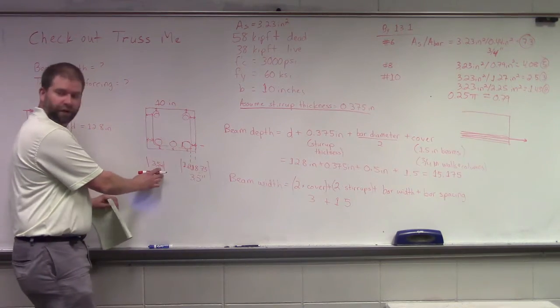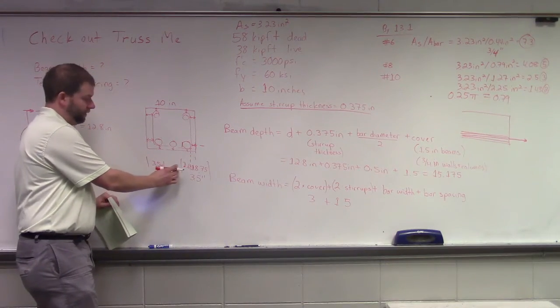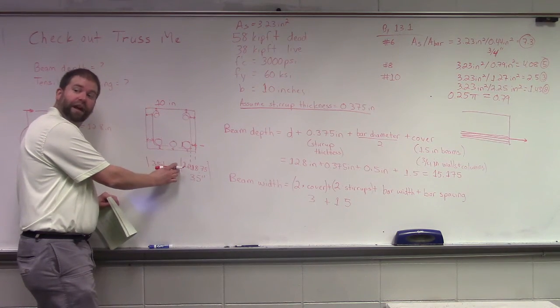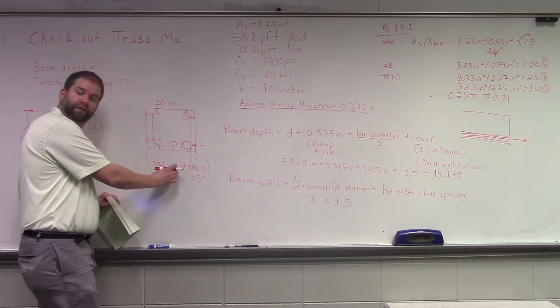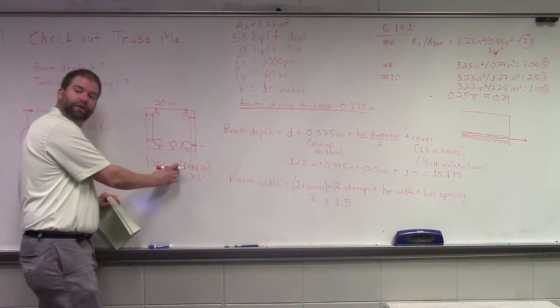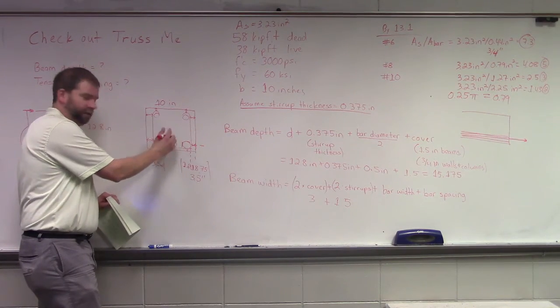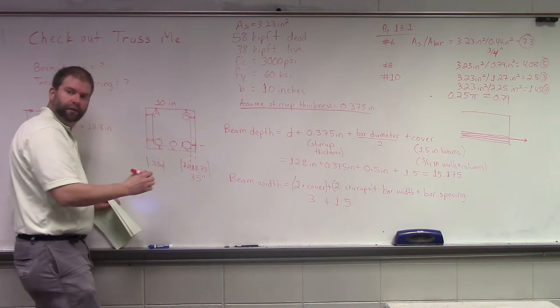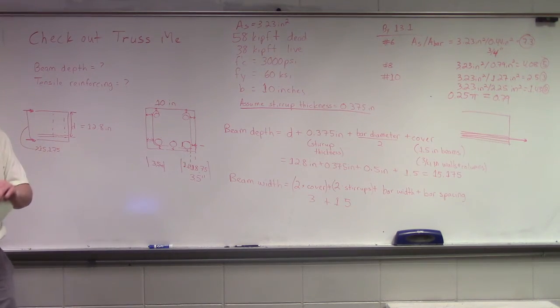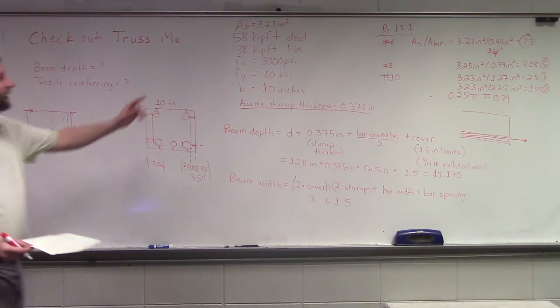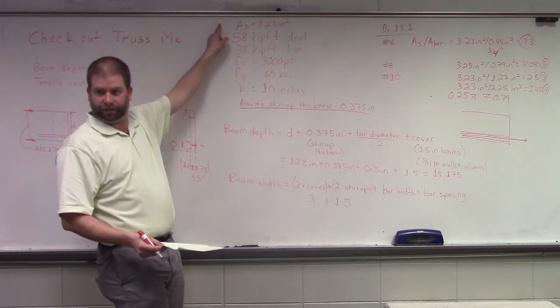So we have 3.5 inches all in over here, 3.5 inches over here, and 3 inches of space in there. Now we have 3 inches of unreinforced concrete. What's going to happen when we load this beam? It's going to crack. Well, the strength of the 2 bars is all that's needed, it'll hold it. We have to be careful. It meets the area of steel requirement.